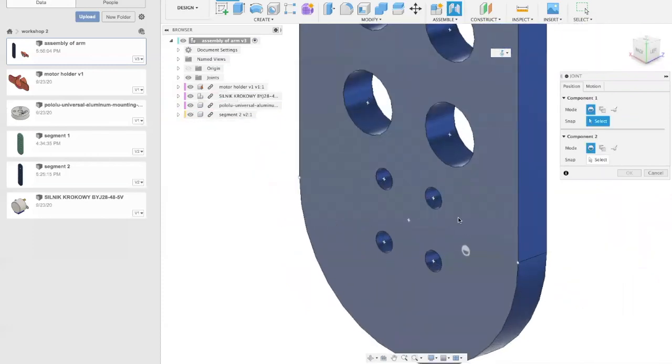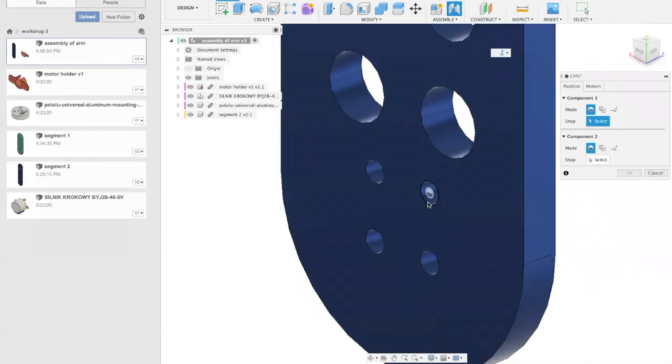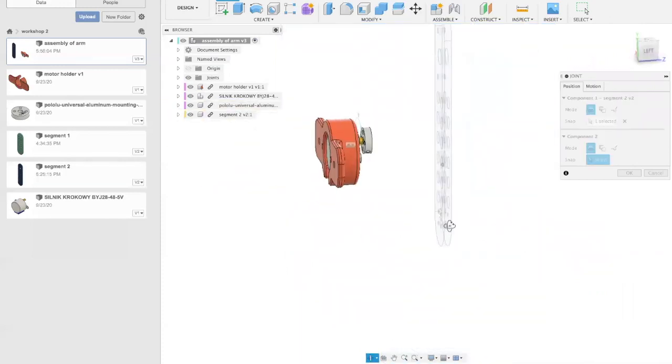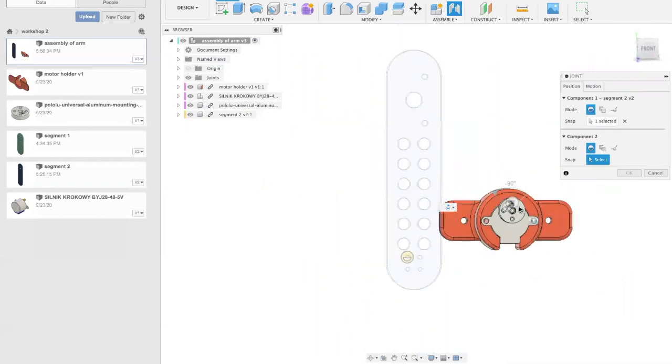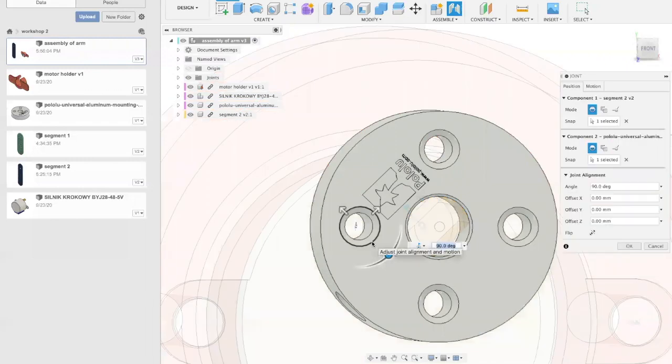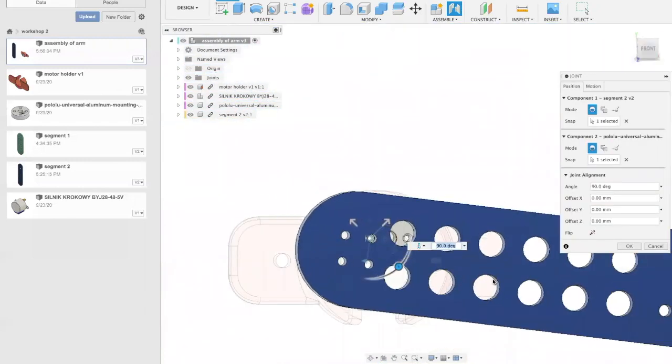And I'm going to select one of these holes on the rim. And what you're going to be selecting will highlight black. So I know that I want to select this rim, so I'm going to click there. And make sure you remember which hole you selected so that you know where you're actually snapping it to. In this case, I want it to snap to this hole, and it should center constrain to that hole.